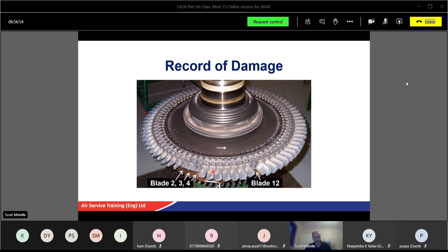Right, last one for today will be the heavy landings. I think we'll do that blade one. Turbine blade with limited damage also requires borescope inspection. Yeah, I mean, as I say, that's why you wouldn't be able to check an HP or an IP with a borescope. The LP you can see from the back by looking at the exhaust, but certain HP you can only get in there by looking with your borescope.